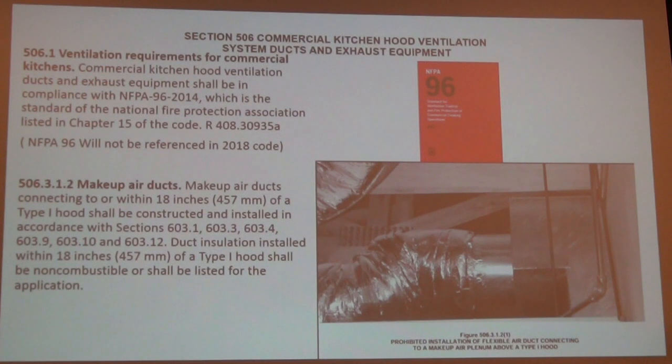And then any ductwork that is attached to that hood has to be constructed according to Chapter 6. And it shall be noncombustible, shall be listed for the application. So basically, they're saying anything within 18 inches has to be sheet metal duct, not flex duct like they're showing here.